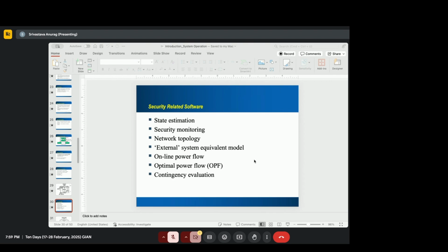In terms of doing it and whether it is useful or not, I will say yes, because the system is becoming more and more active and there are bigger industrial loads, because outages happen in the distribution system, right? Loads are always connected, 99% of the time in distribution, not in transmission. So if you do contingency analysis in distribution, we can increase the reliability of at least the bigger customers, if not the smaller ones. And because there are DERs and microgrids being connected, it will help.